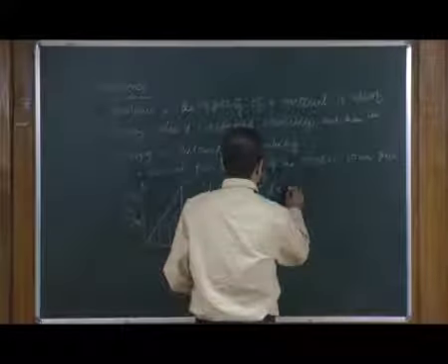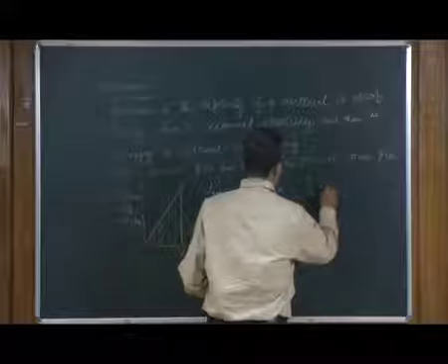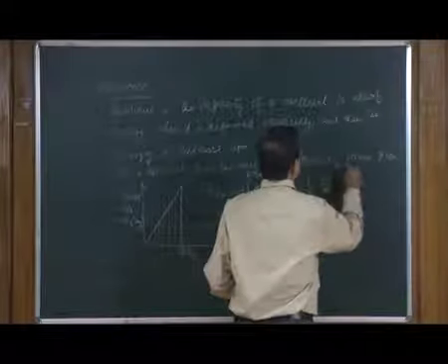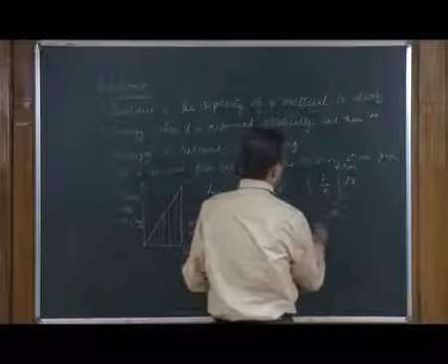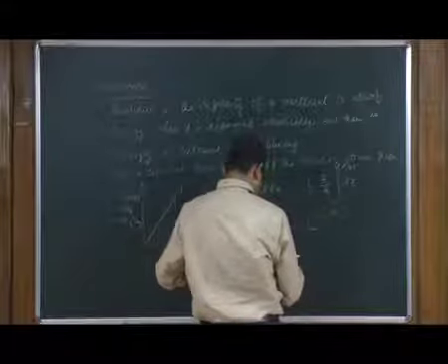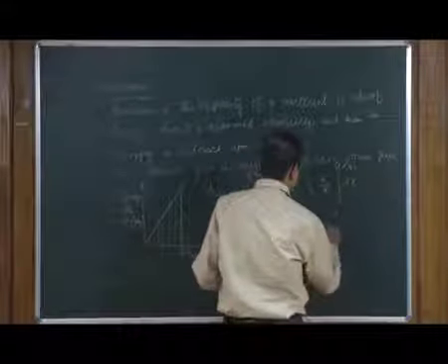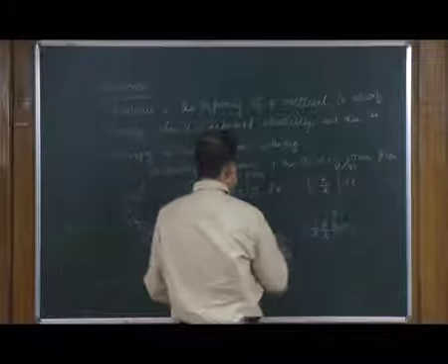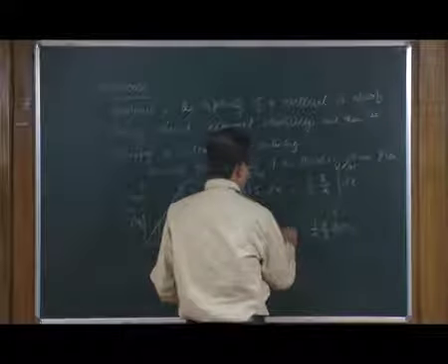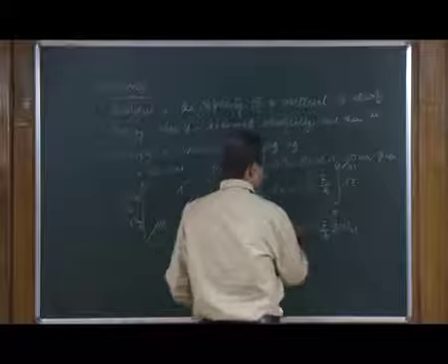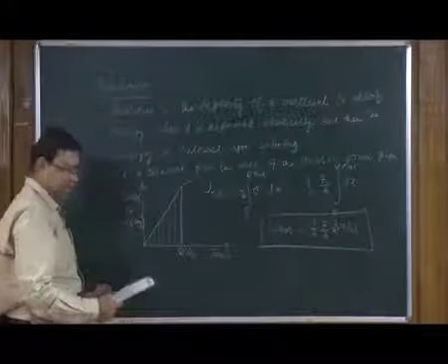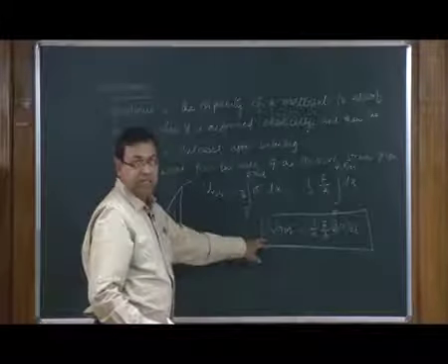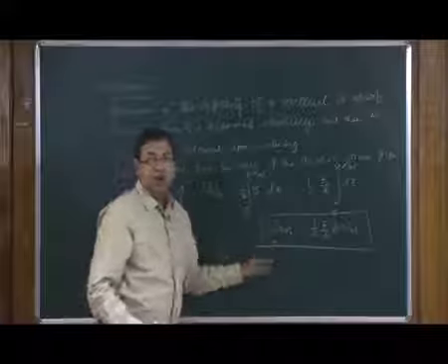So, this is equal to half, F over A, dx integrated from 0 to delta x elastic, which is equal to half F by A into delta x elastic. So, that is the U resilience. This is the energy stored and hence released upon unloading, which measures the resilience of a given body.